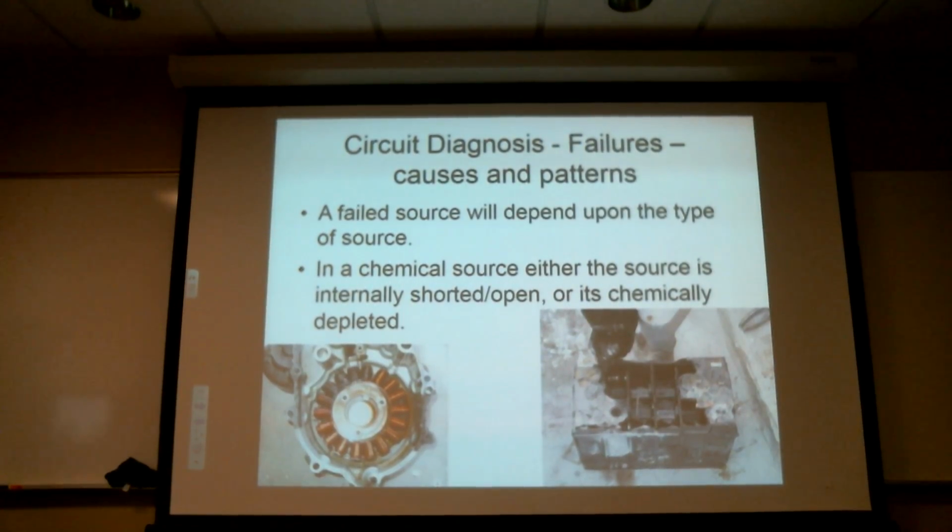a number of things can cause them to go. Primarily, it's either a dead short in the battery, causes it to get really hot, and it starts to melt, or occasionally, and again, you really have to work hard to do this, but it is theoretically possible to where you could have a vent, one or more vents get plugged, and you're in a charging cycle, and it builds up pressure, and it's a pressure rupture.